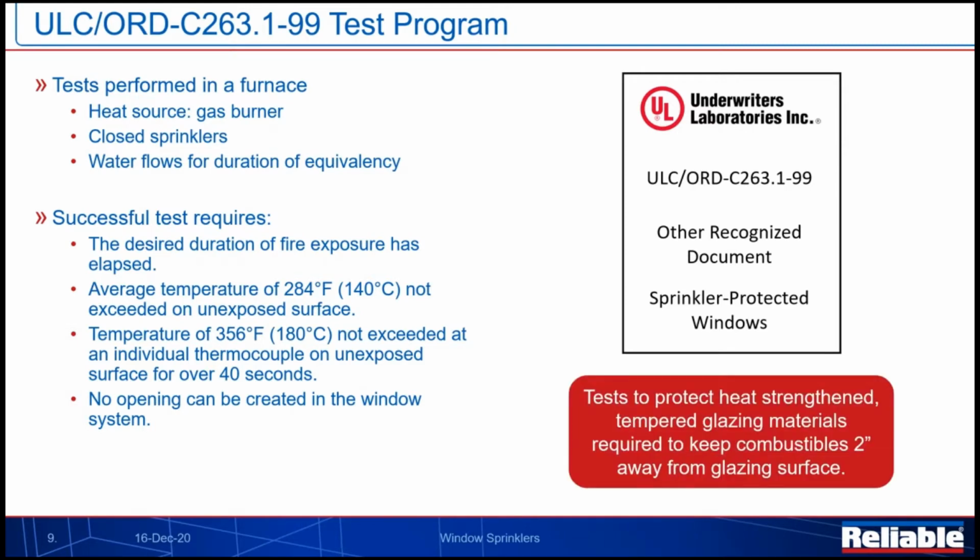This whole test procedure can sort of be more simplified into saying that we're going to test heat strengthened glazing and tempered glazing materials, and we're also going to have a requirement to keep those combustibles 2 inches away from the glazing surface with this type of test.